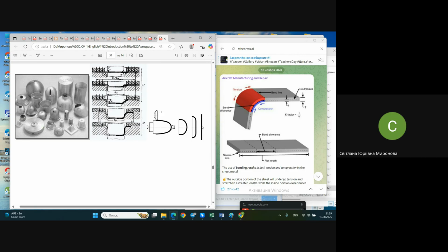And a roller slowly but continuously moves from the central point along this shape, and the shape rotates. And in some minutes, even some seconds, depending on material, depending on speeds and technological mode, you will have a part which completely corresponds to the final shape that you need. But in this case, it's not a press, punch, die block. It will be something like a punch, but this punch will rotate, and it will rotate in machines very similar to a turning machine, or it's also called a lathe.